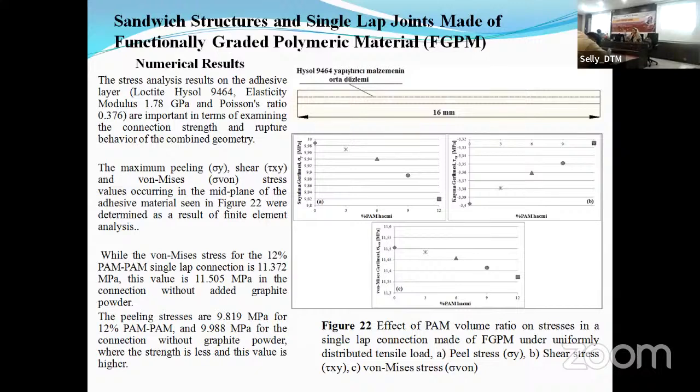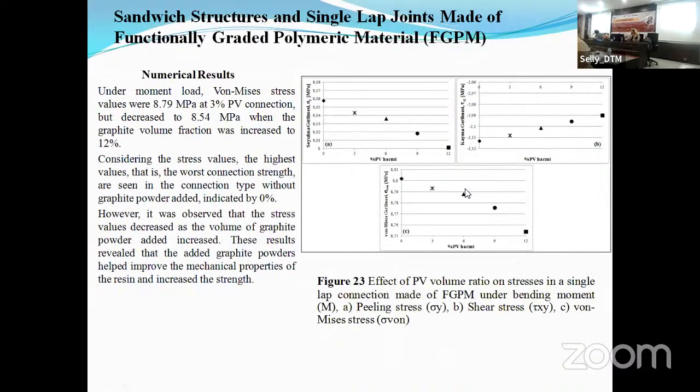Then we ask, please tell me what is the shear stress in that path? What is the von Mises stress? What is the deformation? Just on these specific paths. So the path was chosen in the midline in the adhesive, and the overlap length is 16 millimeters.